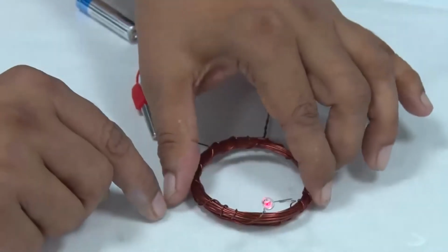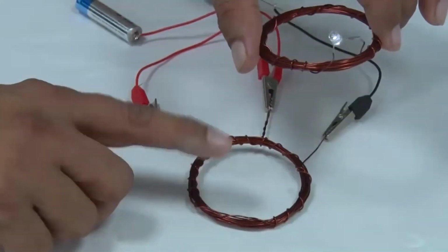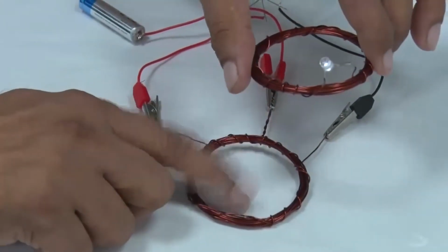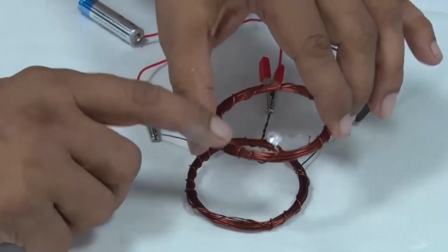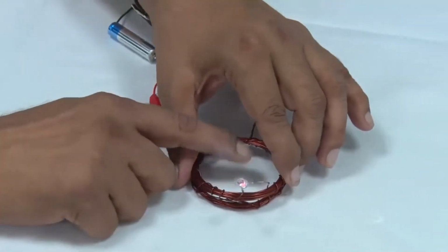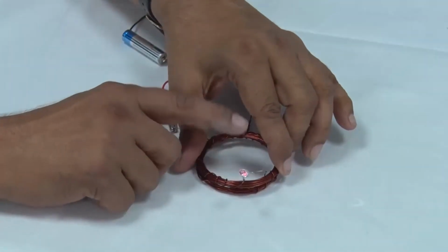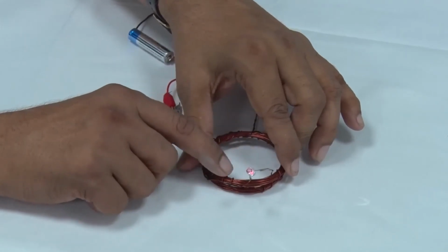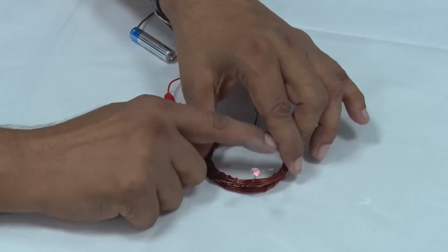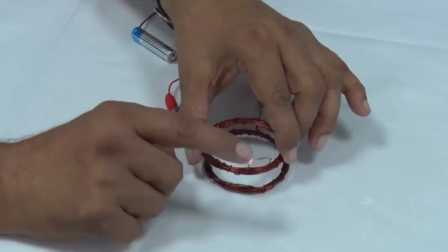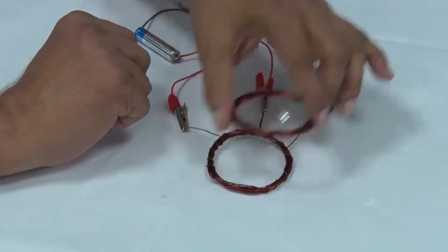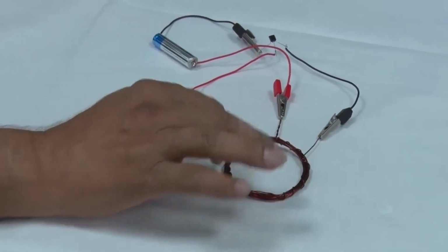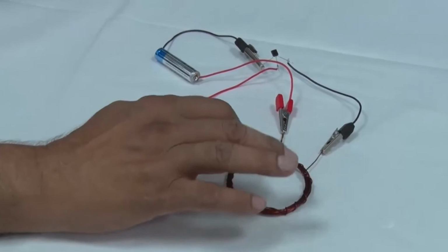You pass a time varying current here, and the time varying current produces a time varying magnetic field, and when you bring this other coil here, the time varying magnetic field gives you time varying magnetic flux, and the time varying magnetic flux creates an EMF, and that drives a current, and therefore it glows. So that means you have a time varying current here, some kind of an alternating current here,